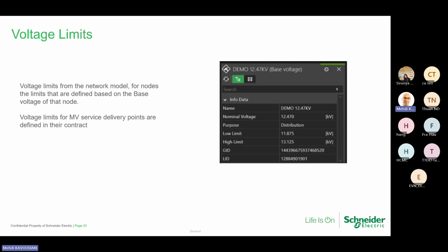Voltage limits for lines and transformers are the ones that I was showing. For voltage, it's not per element, it's per system. But you can say, for this 12 kilovolt level, whatever your measuring voltage is, you can define it for that voltage level. It's 5% higher, and that's actually very high. Two levels up, two levels down.